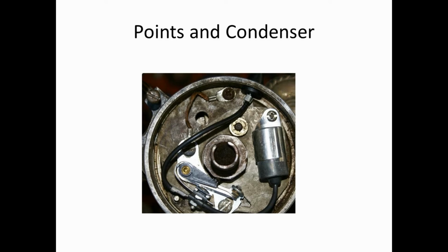These have completely gone the way of the dodo from a production standpoint, but I have run into quite a few of them. You'd be quite surprised. Generally in marine applications, for some reason, they were used up until later years. So we have our cam, which is attached to the rotor shaft. We have our breaker points, which ride on the cam, and the cam pushes the breaker points open and closed.